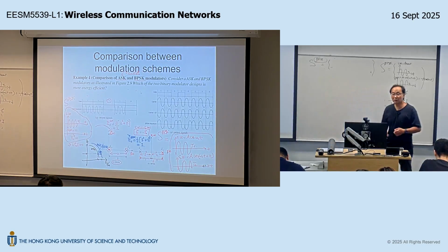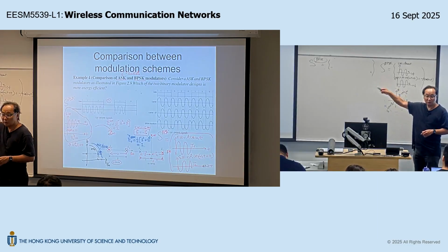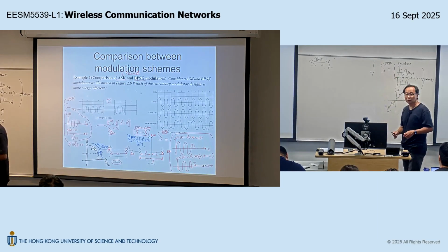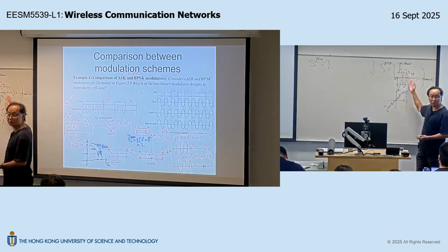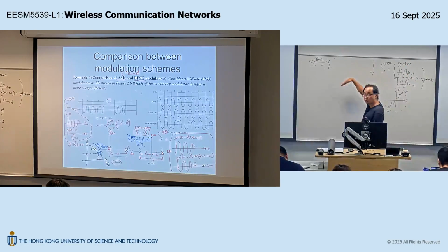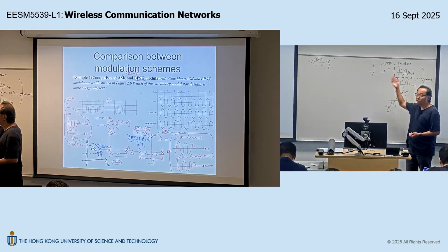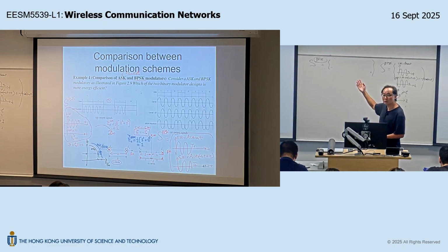Now for those who have studied digital modulation before, BASK is called the digital version of AM, okay? BPSK is called the digital version of phase modulation, because obviously you're using the phase difference to signal between 0 and 1, whereas the ASK is using the amplitude to signal 0 and 1. So that's why the names come after this time domain feature. And then the third one is BFSK, the digital version of FM. That means you expect it's using different frequencies to signal between 1 and 0.